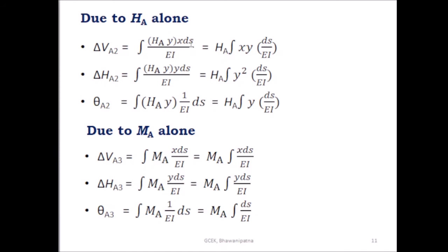This is the moment m1. This is the moment due to HA alone, and this is the moment due to the unit vertical loading, HA y into x ds by EI. So after simplification, HA integration xy ds by EI.